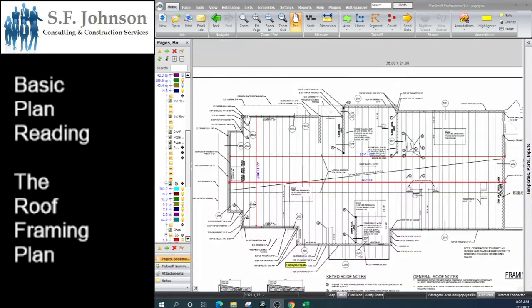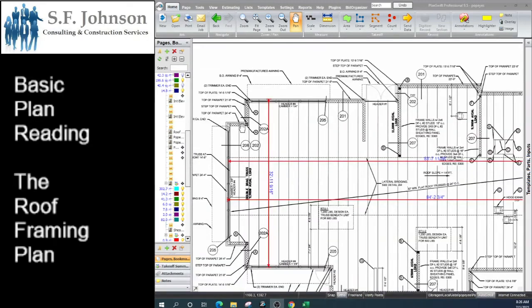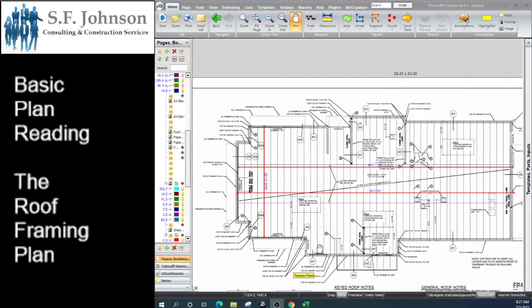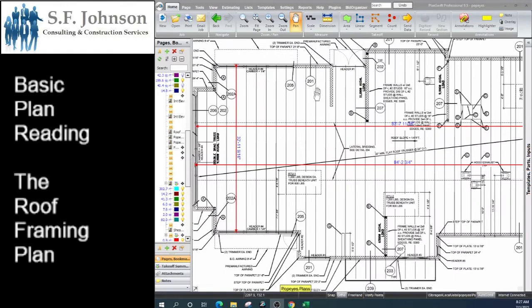So for the purpose of the estimate, you could do it two ways. If you use a good cost book, it's going to give you the cost per square foot, and so you're going to determine how many square feet of roof you have. Or if you want to do it more specifically, you're going to determine how many roof trusses you have of each of the individual lengths. From here to here, pretty much they're the same length, and then they get bigger here to here. And those are the same length until we get to here, and then they get larger when they get here. So two ways of doing it.